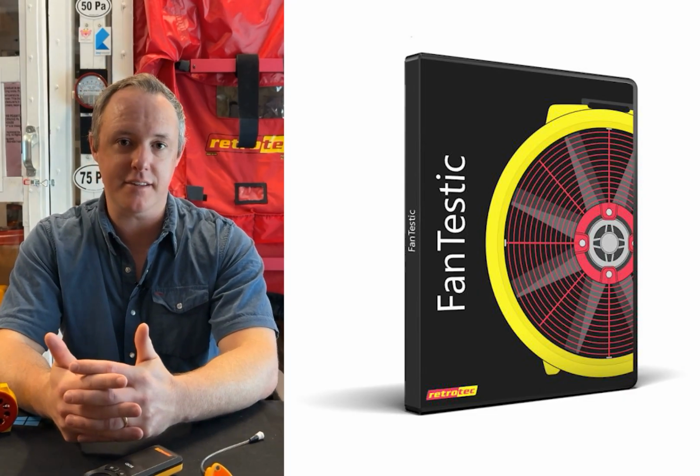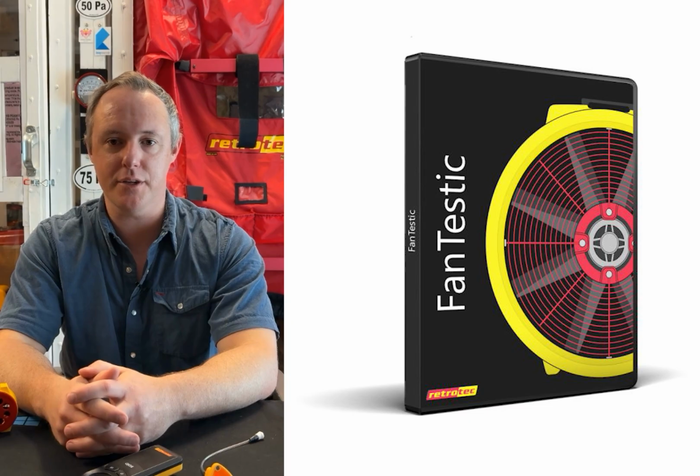And so if you're choosing to go this route to neutralize the attic space with a second fan, where things get a little bit tricky is where you're trying to do a multi-point test. So anytime you're controlling two fans where you're trying to do a multi-point test, the best way to do that is through software. And with the Retrotec gear, we have Fantastic. That's our multi-fan software that we use in the commercial industry all the time, where we're running multiple fans to test large volumes of space. And so depending on where your attic access is will determine how you hook everything up in the software.